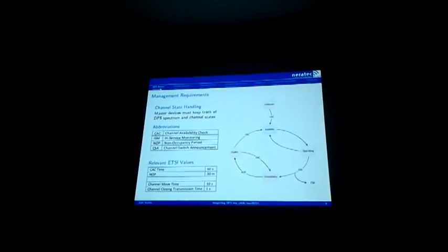During operation, you must do in-service monitoring. That means constantly looking for radars. In case you detect something, the channel becomes unusable, and at the same time you immediately have to move away from this channel and stop transmitting. Before doing so, you are allowed to do a channel switch announcement to let your stations disconnect from you.